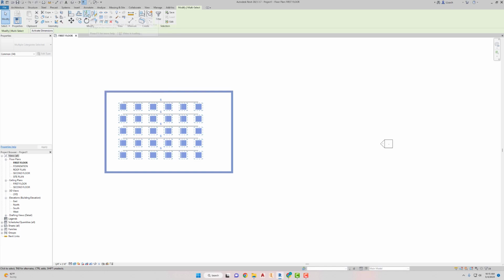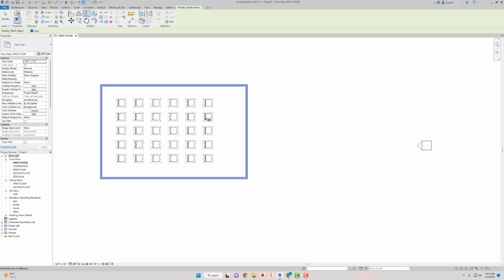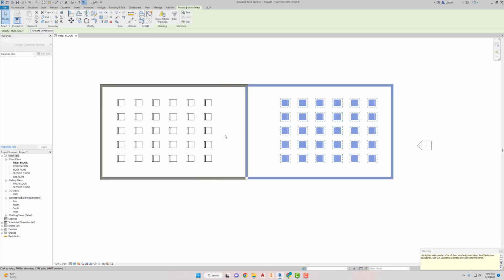So with the pick axis, it's like a pickaxe, like you're gonna cut some ice in the tundra. Anyway, I'm gonna select the pick axis tool. And then here, you just select an axis that's already somewhere on the drawing, which is probably, in this case, not what I would want to do. Let's say I want to pick the center line of this wall here as my axis. So it's gonna mirror those around the center of that wall.